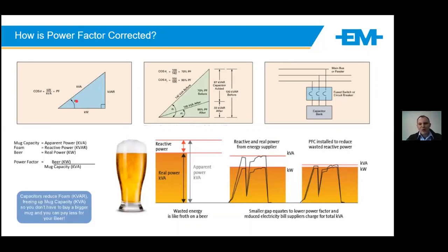By calculating this power factor and the required kVAR to improve the power factor to 0.98 or 1, we would need to bring in capacitors or capacitor banks, which are in parallel with the circuit. The system would measure, see the requirement, and bring in those banks.